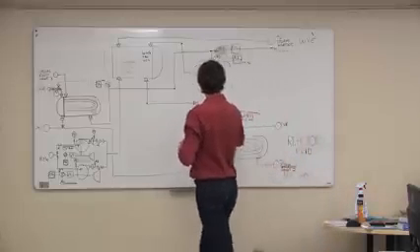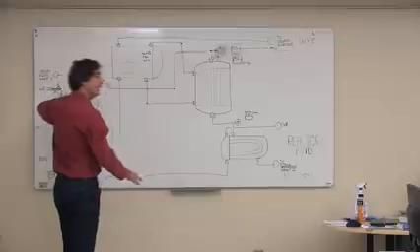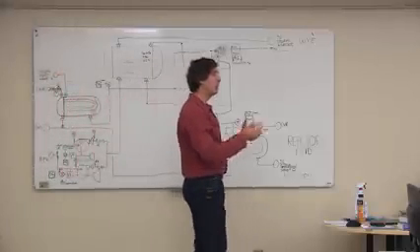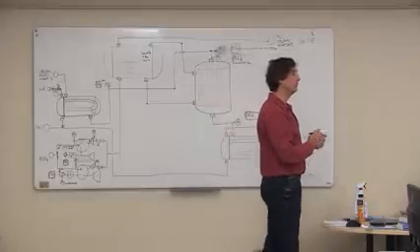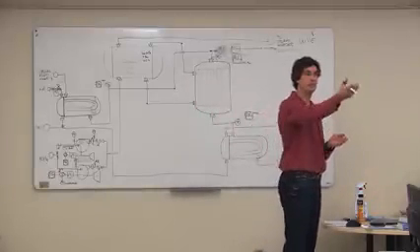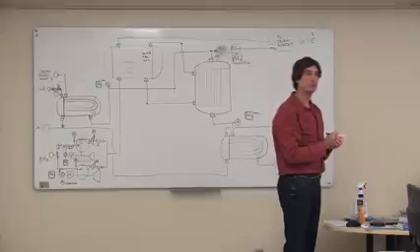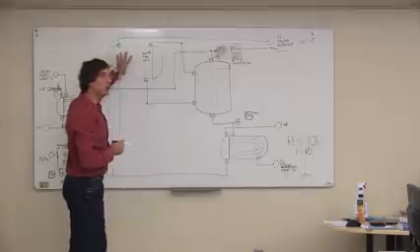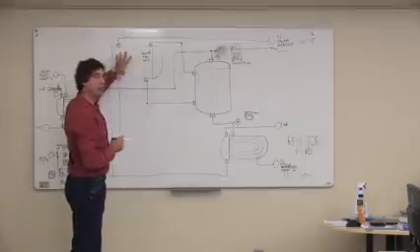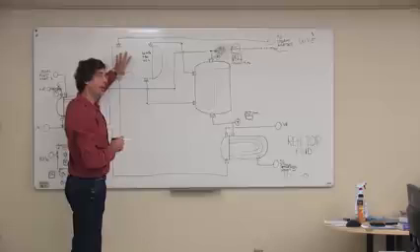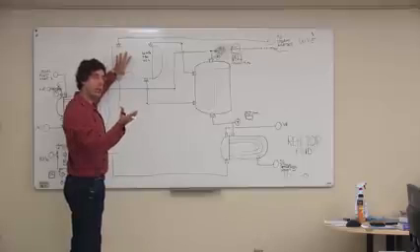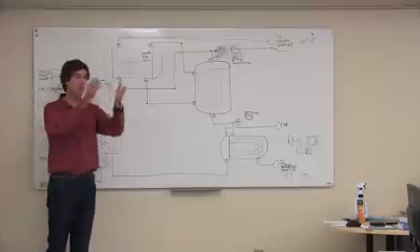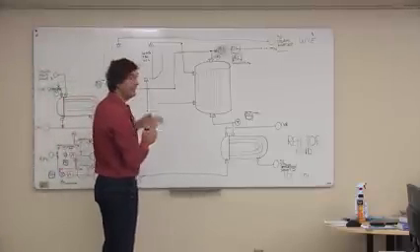Yeah, if it got too hot, we could go back and reduce the flow rate of syngas, but most likely the pressure in the system would start to drop. Okay, so if we change the pressure of the steam drum here, then it changes the boiling point. If it changes the boiling point, it's changing the temperature. If it's changing the temperature, it's changing the LMTD of the heat exchanger. Bingo. So what we need is what?